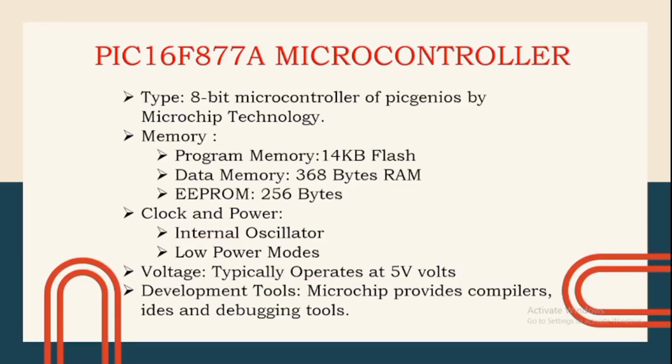For example, we used its digital I/O pins to connect the tactile switches and LCD, and timers to control the wash cycle duration. One reason we chose this MCU is its compatibility with MPLAB tools and ease of simulation in PICSIMLAB.